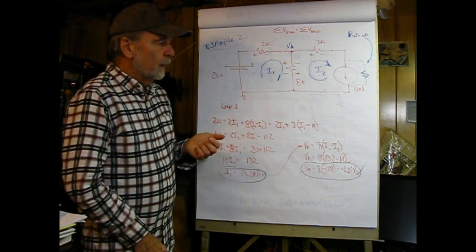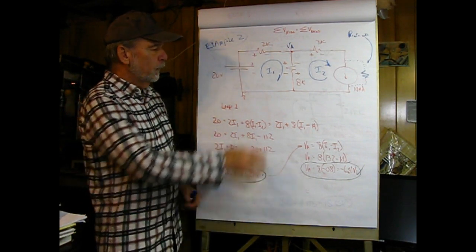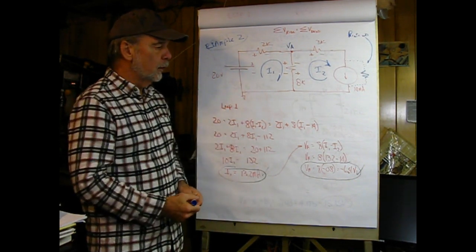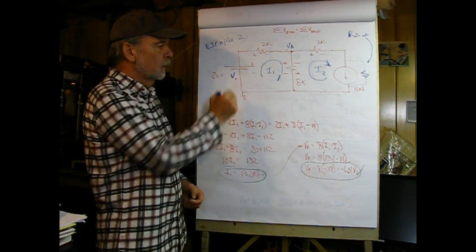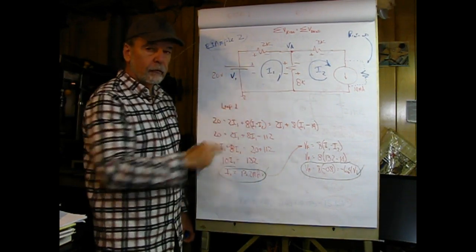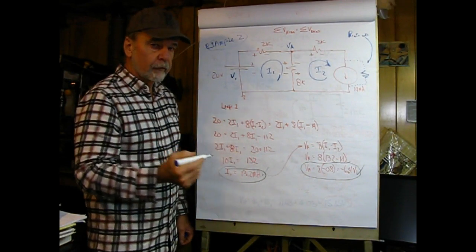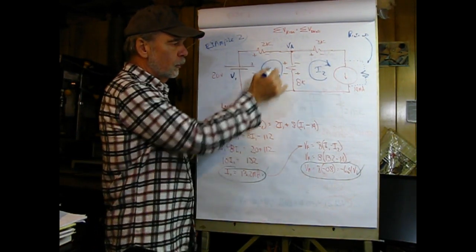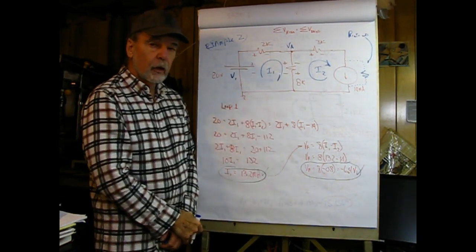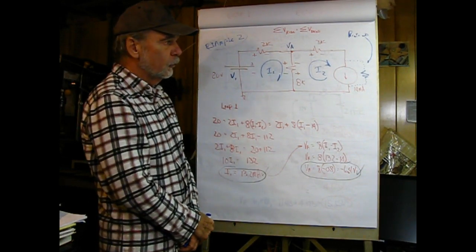Let's look at another example that uses a current source. So in this case, I'm letting my V1 here be equal to 20 volts. Again, I draw a mesh current for I1 and mesh current for I2 as before, and then I very carefully wrote down the voltage drops across all components with respect to each loop.